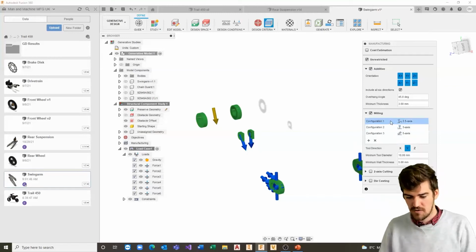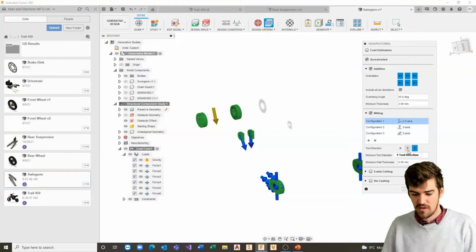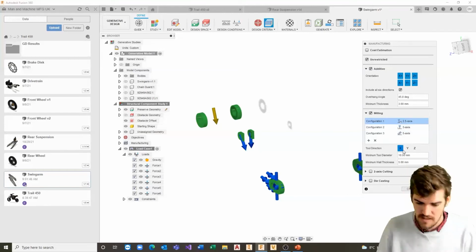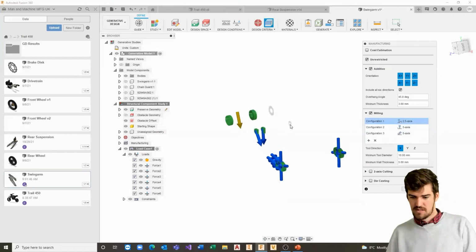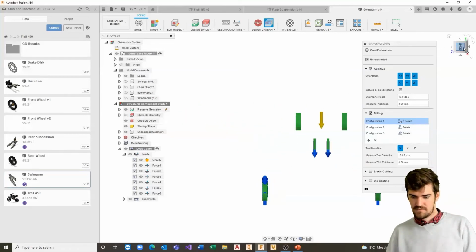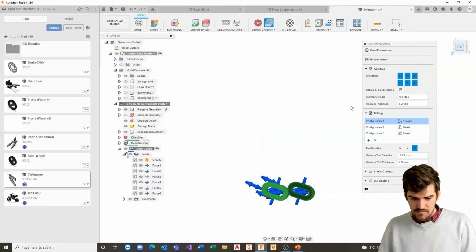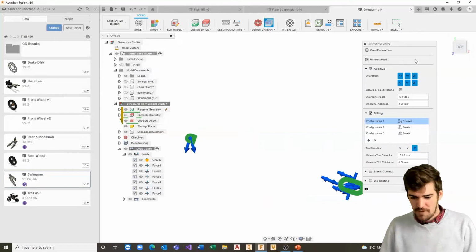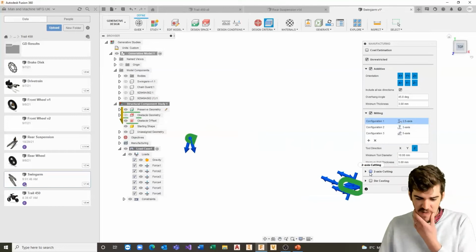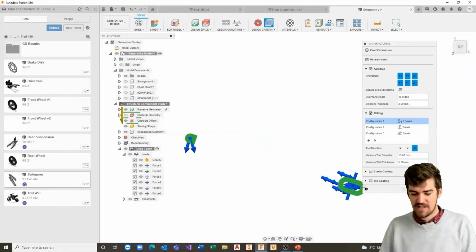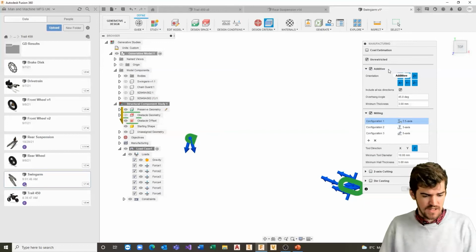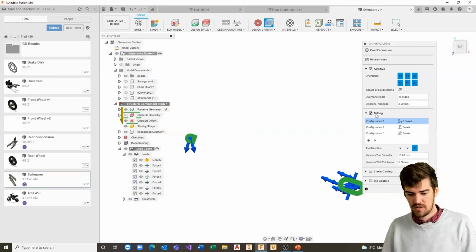For the 2.5, you'll just need to select one of the tool directions. In this case, I'll probably select, let's see, Z. Or Y, one of the two, doesn't matter. We've also got the ability to set the 2-axis cutting or die casting, and you can add all of these to the studies itself. So for the one I did earlier, it was essentially going to be the unrestricted, the additive, and the milling. We can have a look at the other options at a later time as well.